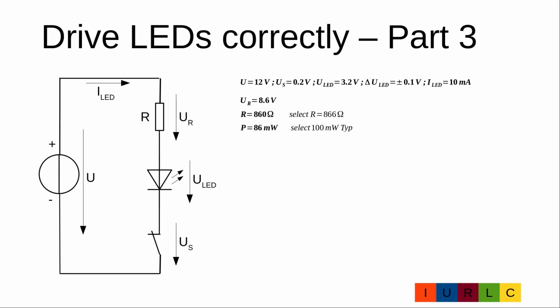The brightness tolerance of an indicator background illumination has different sources, e.g. the brightness tolerance of the LED, the resistance tolerance of the pre-resistor R, the tolerance of the supply voltage, the tolerance of the voltage drop on the switching transistor, and the forward voltage tolerance of the LED. I want now to calculate the brightness tolerance, which is caused by the LED forward voltage tolerance.